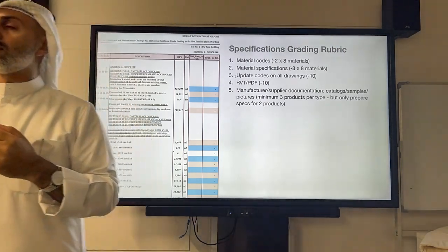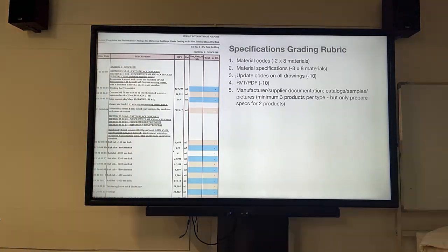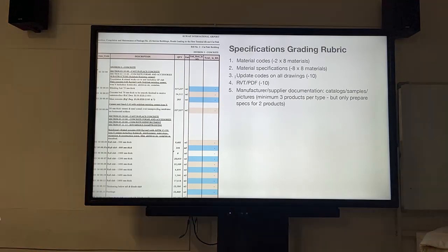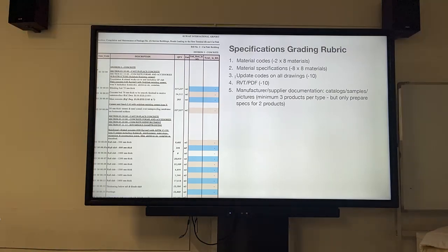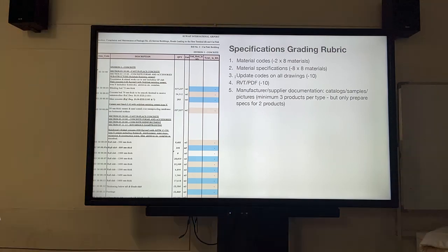The specifications, by the way, you could do outside. In Revit it's not that great to do a table and text and align things, but you can do it in Excel or Word, export as a PDF, and then import that PDF onto your sheet directly. No need to make it complicated, unless you're comfortable and you just want to do it straight in the sheet, that's fine as well.